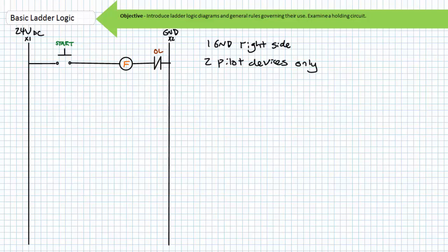Ladder logic diagrams only show pilot-rated electrically active components like switches, pilot lamps, control relays, contactor coils, and the solenoids of solenoid-operated directional control valves. Primary devices like hydraulic components or contactors aren't included. These devices would appear in the primary hydraulic or electrical schematic.